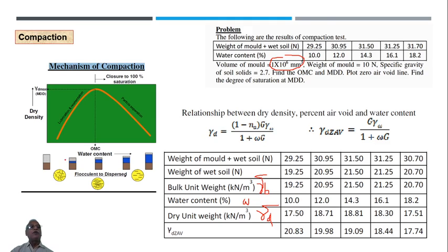And we have removed all the air voids, and then if we say only the volume is this much only, right, from the top of this water up to this bottom, these air voids are completely removed and the volume is only this much. Obviously, what happens is dry density will be maximum, because this volume we are removing, right? It is the weight of soil solids.